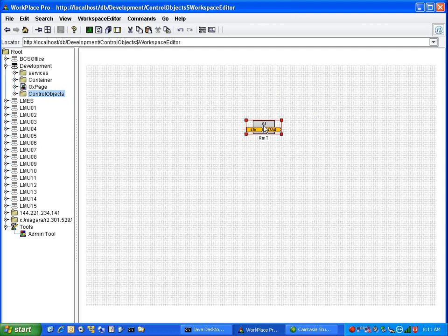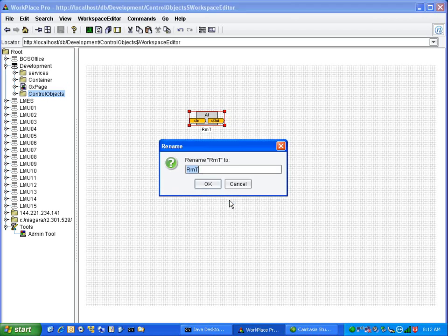The other thing we use these for is global purposes. Say we have a job with an enterprise server and 3 UNCs. We have one controller out there that has an outside air temperature sensor. Of course, that means only one UNC provides this outside air temperature sensor. We need to share it with all the controllers on the job. So a lot of times we'll take an object like this.